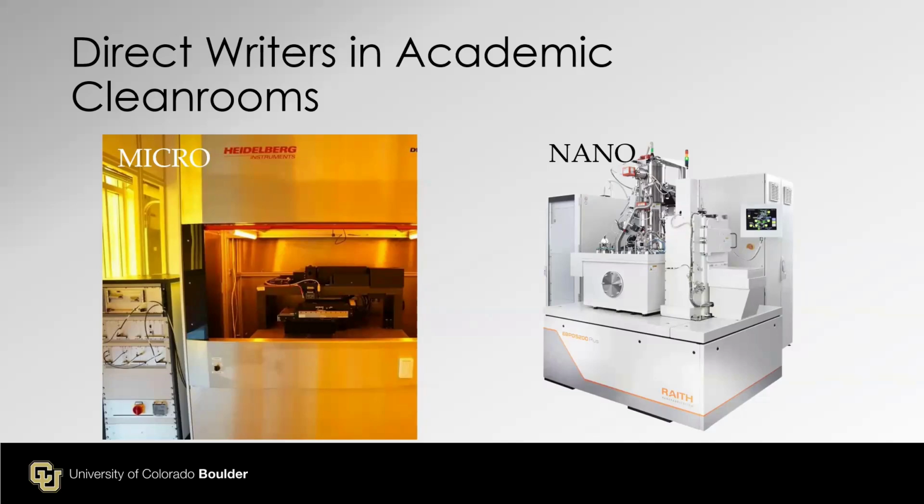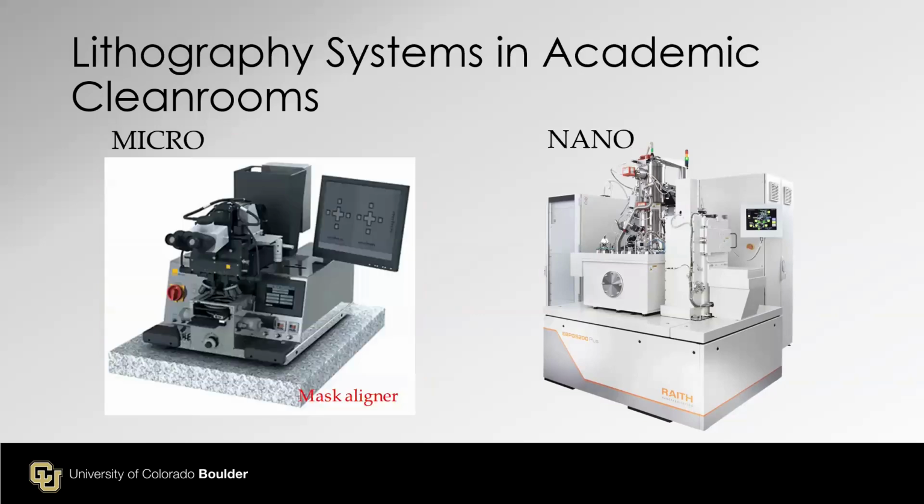It uses an optical beam, and this is a direct writing system. So no mask, and actually the Heidelberg mask writer is mostly used for making masks. We use a contact printer for microfabrication, but this is the indirect writing system. So we need a mask for the mask aligner, while EBL, the electron beam direct writer, does not require masks.